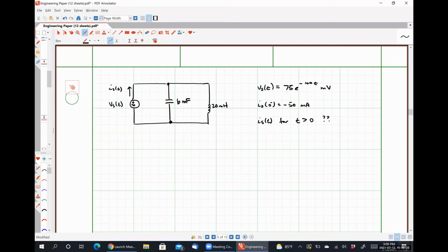All right, so now let's get back to what Sarah said just a moment ago. It's going to be either KCL or KVL, which is absolutely correct. This is a single node pair circuit where everything is connected in parallel. So I would argue that we should be doing KCL, Kirchhoff's current law, since that is how we handled all of our single node pair circuits back on the 3rd day of class, right? KVL would be less appropriate because since everything is in parallel, all we're going to find is that the voltage drop over everything is the voltage drop that we're given, which doesn't really provide us with any new information.